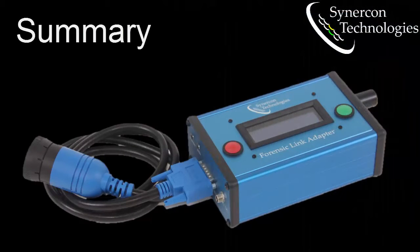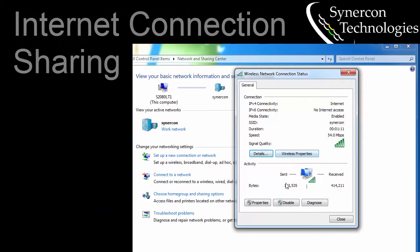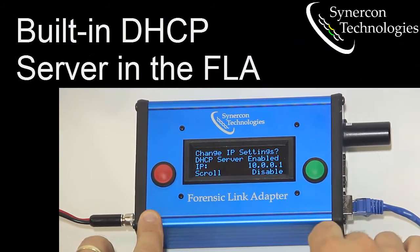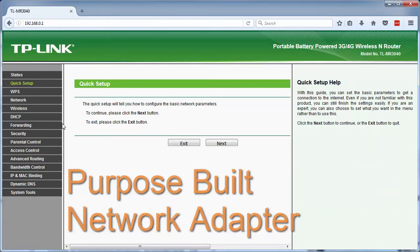In this video, we've gone over 4 different ways to connect the Forensic Link Adapter to a network. The first was using a direct LAN connection. The second was using internet connection sharing through Windows. The third was using the DHCP server built into the FLA. And finally, using a dedicated network appliance to connect and build your own network.